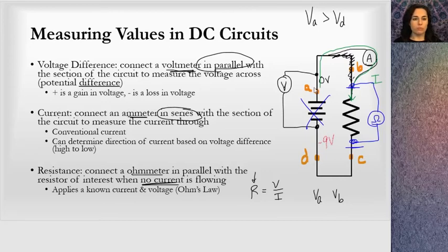But when you choose different points, then that's really asking, do you understand how a circuit works? So when you have 2 points that are along the same wire, all of those points along that wire, it's a conductor. They're all at the same potential. Those charges have 0 resistance of moving in that wire. So if it's 0 volts over here, it'll be 0 volts over here as well. The current's going to flow freely from A to B, and the potential at A is equal to the potential at B.